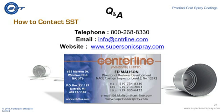When we pull tensile bond strengths, typically evaluated using ASTM C633, the same method for thermal spray coatings, we're typically going to get between 6,000 to 10,000 psi. So that's not near the tensile strengths of typically the wrought materials, which are in the tens of thousands of psi. I don't think there is a coating process that can achieve the same tensiles unless you get pure metallurgical bonds like a welding or something in that nature. So typically metal coatings themselves in the thermal spray category will get anywhere between 20 and 30% of the raw material's tensile strength.